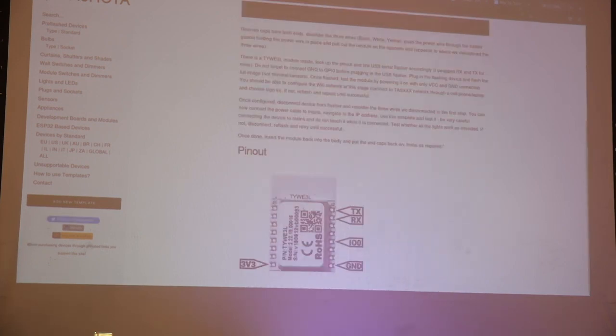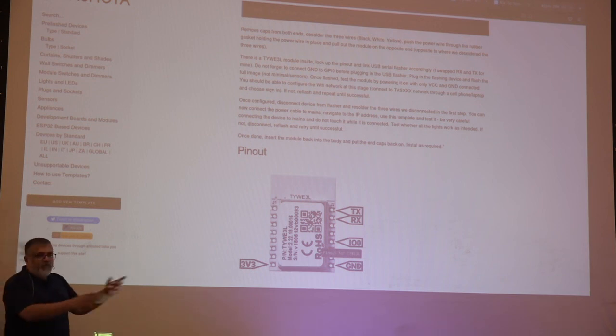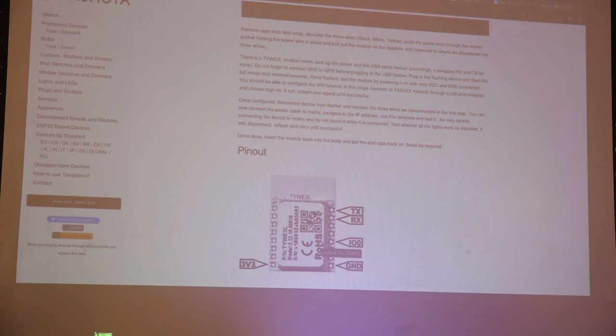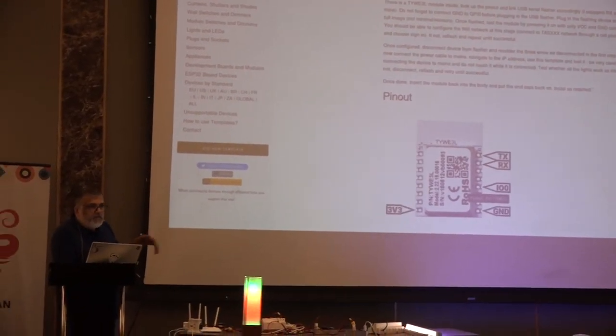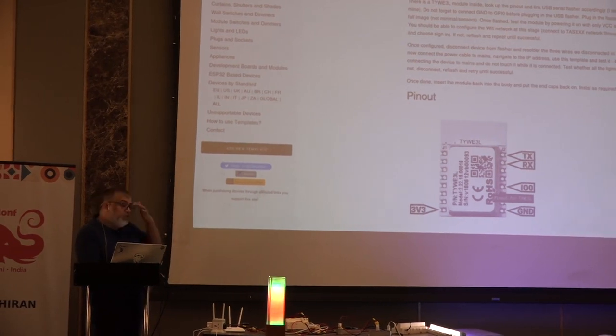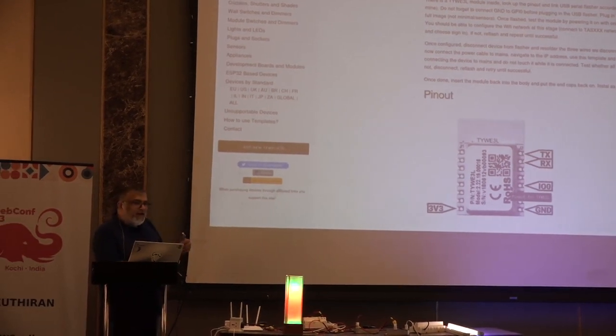And that's the best part, because now if you purchase that tube light, you know exactly what the pinout of the microcontroller looks like, and the process of flashing it is documented. Yes, the challenge here remains that we have to open it up. We have to take the tube light apart. We have to solder 5 wires, and then we get the ability to flash. So that is a bottleneck.